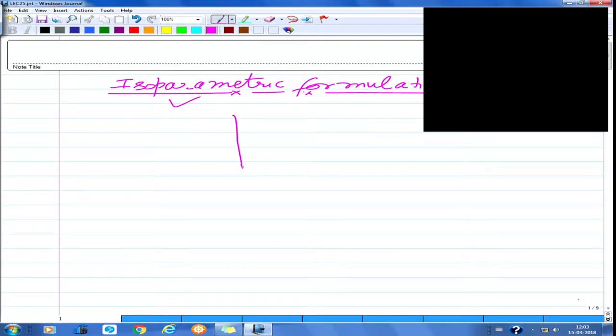So let us say that we have an element in the physical coordinate space which is actually a rectangle, but it's 8 noded. These are the corner nodes and mid side nodes. To simplify our calculations, let us say our coordinate system has its origin right here at the first node. So this is local node 1, 2, 3, 4. This is typically the numbering scheme, although you can actually use any numbering scheme for the local element numbers.